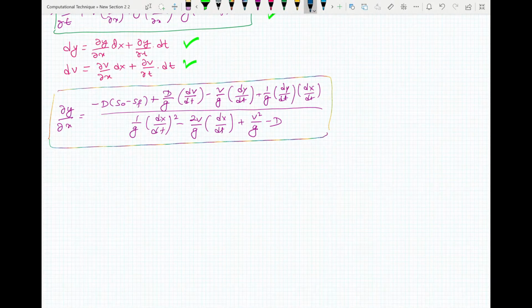Now in cases of flood, what will happen is that you'll have different surges, and in the surges at a point of discontinuity you'll have two surface slopes at the point of discontinuity which will have no relation to each other. Therefore your dy by dx at that point should be indeterminate. Therefore this can be equal to 0 by 0. Now in this case you can assume your numerator to be 0 and your denominator to be 0.